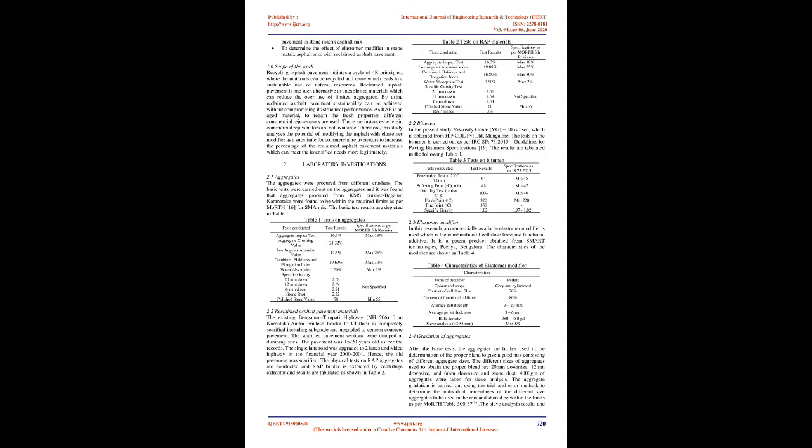1.5 Elastomer Modifier. The Elastomer Modifier consists of a functional additive, which is a smart solution to improve the properties of mix around the globe. It gives better durability, convincing anti-rutting characteristics, better aging resistance and enhanced performance. Apart from this, it is an alternative way to achieve reliable modification of bituminous mix close to the same performance level as modified bitumen.